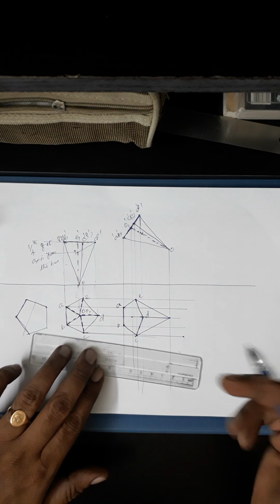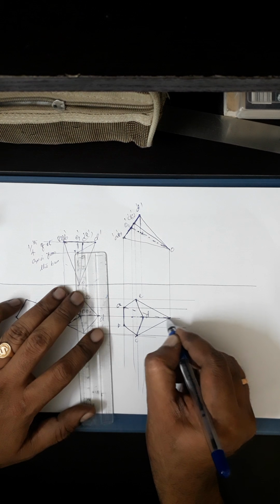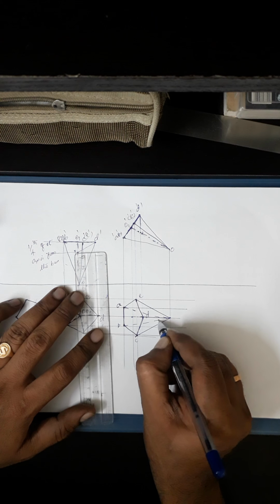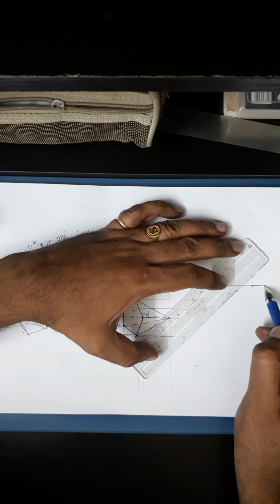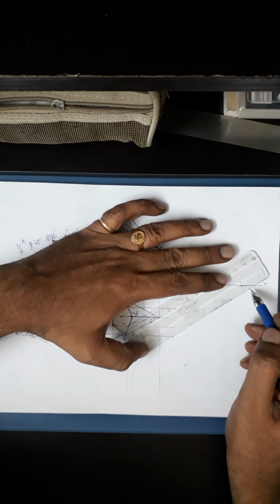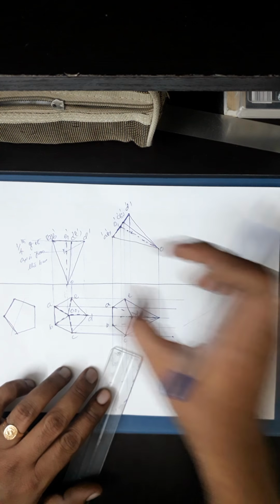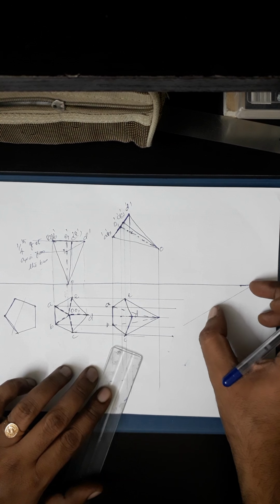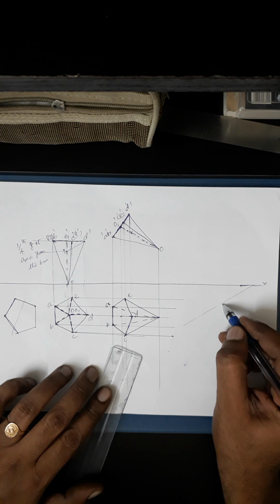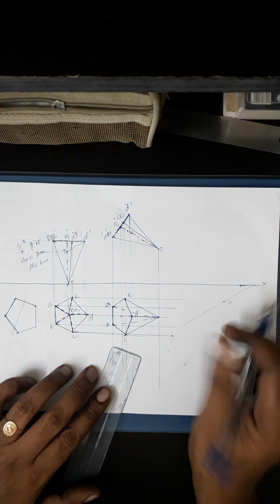If you find the three words, no need to take beta, right? So these are the invisible edges not joined. So go for checking out the edges which are not joined. When they say only the axis is inclined, then you go for finding beta, right? So go for taking this length. Anywhere you can mark from here or anywhere at the point. If you want to start the view from this point, you can take that as O, then you take the true length over here, true length of that, 60 mm.